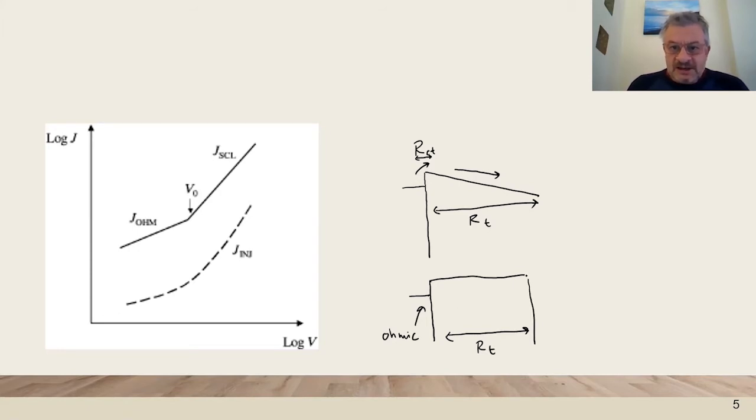So then we can check this quantity because a transport resistance in general must be proportional to the thickness. So if the total transport resistance is proportional to the thickness, then we are in transport limited regime. Otherwise, if the device resistance is independent of the thickness, then it will be controlled by injection. And this we need to check experimentally.